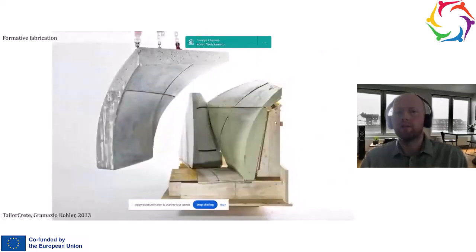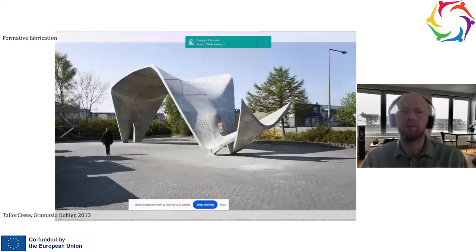After that, the sand was removed, and the wax was also removed, concrete was poured, and they got the final concrete shape of the panels. So casting might be an interesting solution if you want to get a concrete structure that has a nice relief structure, as shown in this example.